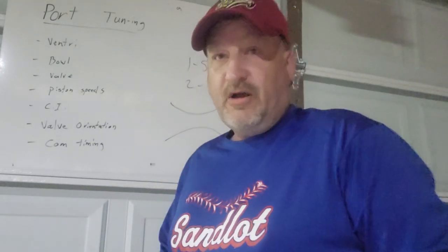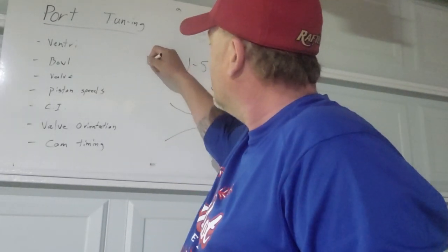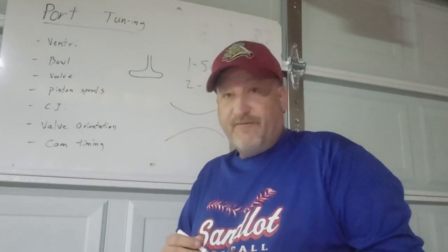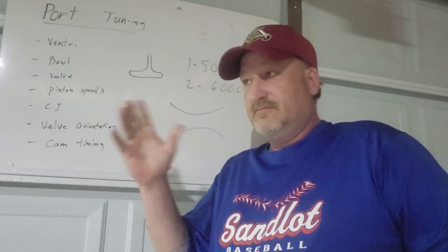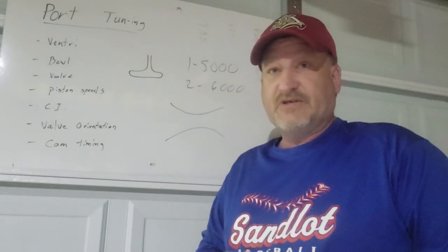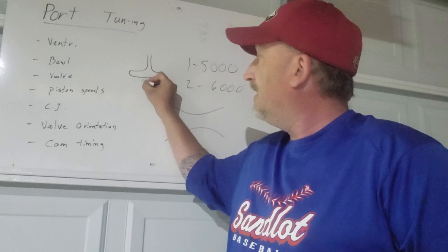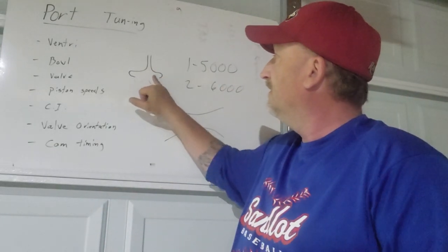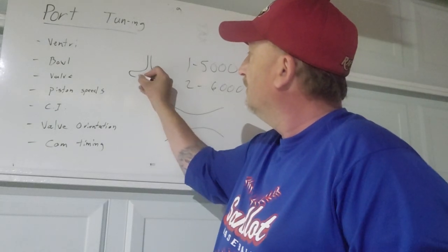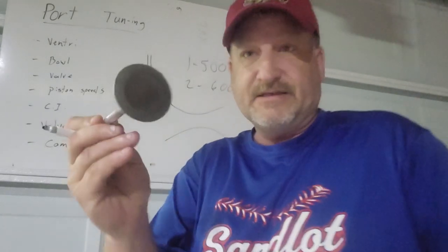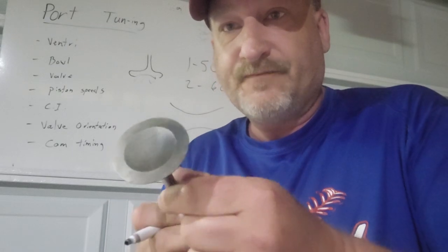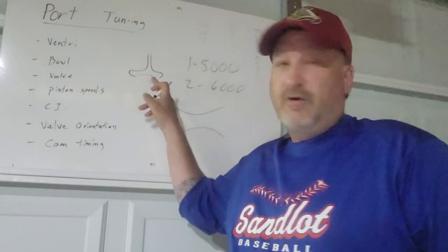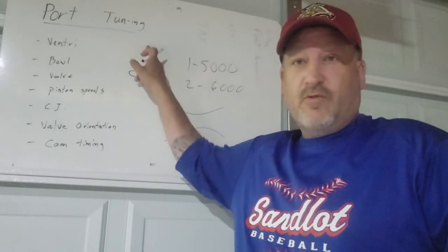So with all valves, when the valve is closed, either on the exhaust stroke or the intake stroke, there is pressure that builds up underneath the valve. And if you have a cupped valve, such as this, let me see if I can get the right reflection, the depth and the size of this cup will also tune the amount of reversion that goes back around the valve.